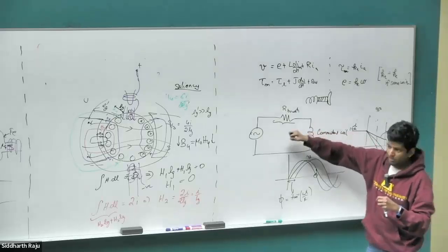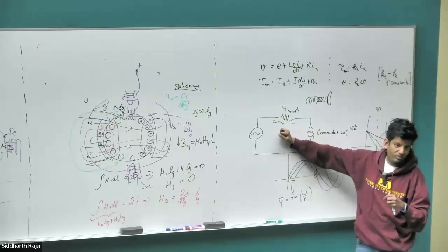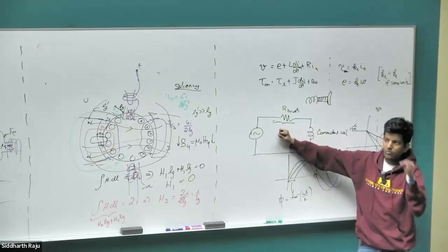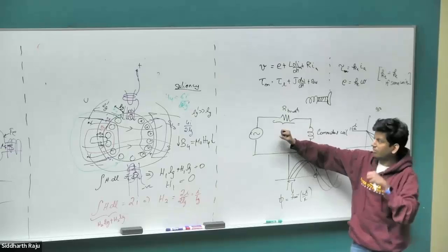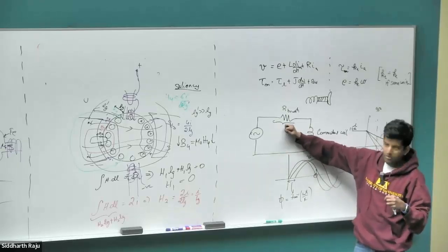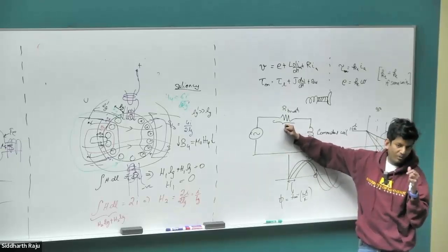Its advantage ends up being its disadvantage as well. It has quite a lot of resistance. Right? That means the current flowing through the armature on all the coils, not just the commutating coil, is going to drop a huge amount of power in this commutator brush that we have.